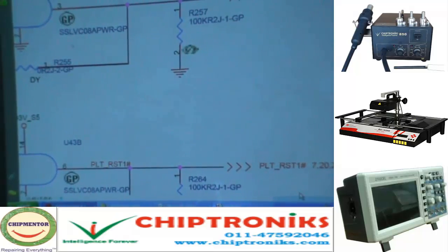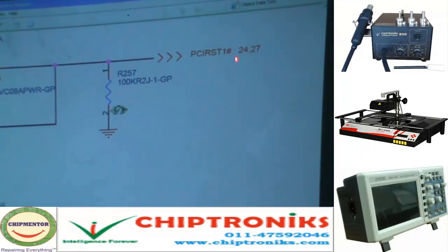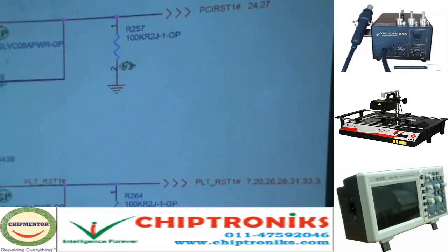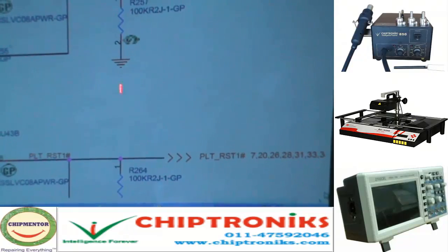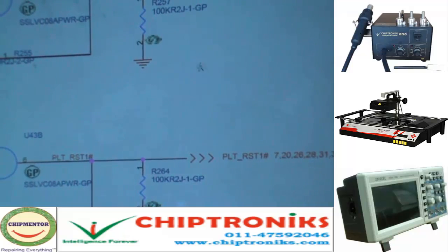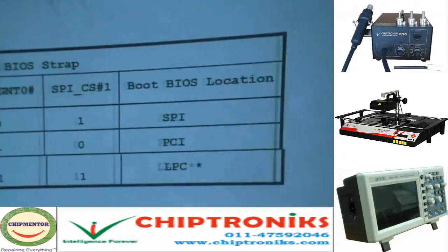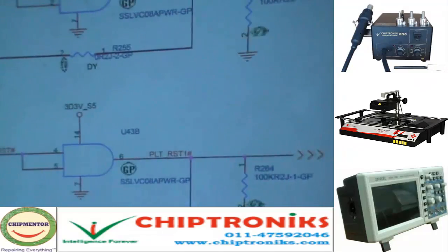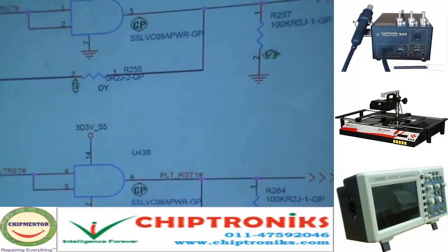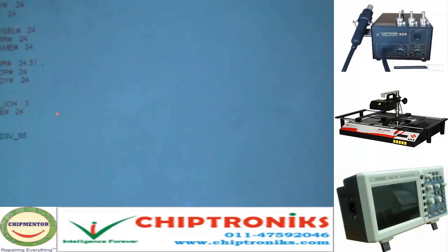So we have seen there are two important signals in this page, PCI reset and PLT reset. We can measure this signal across these resistors. Let's go back to page number 19 and see if any more important things are there in this page.